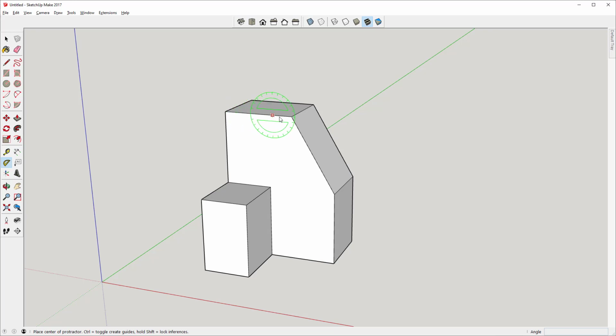from this line, like before, I would want to start here, so I'm going to click and release. I'll come over here. I'm measuring from this line, so I'll click and release, and then come down here. And once again, I can see down in the measurements window, there's an angle there. I can enter an angle. I'm going to enter 20 and tap the enter key, and there is my line that's 20 degrees from that